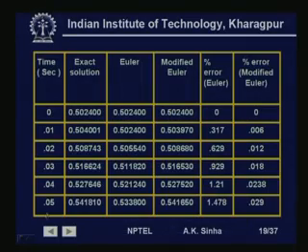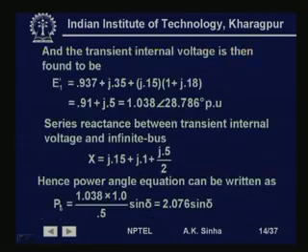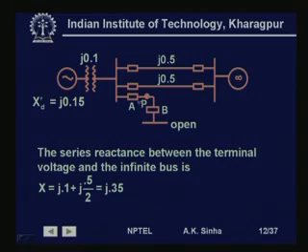Now, in this case, we have plotted the swing curve when the fault is on all the time. If the fault would have been cleared, say after 0.05 seconds or so, then the change we get will be in the expression of Pe, that is, Pe post-fault will depend on the condition or the transfer reactance. That is, if this fault is cleared by opening the circuit breakers at these two ends, then again the system returns back to its normal transfer reactance, which is j0.5 per unit only. So, in that case, again the relationship for Pe will be given by this relationship.